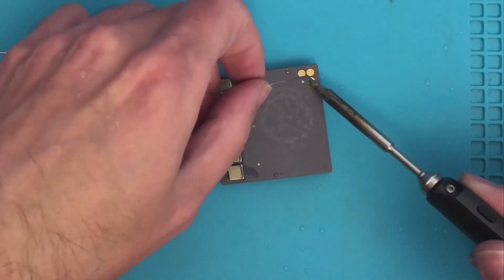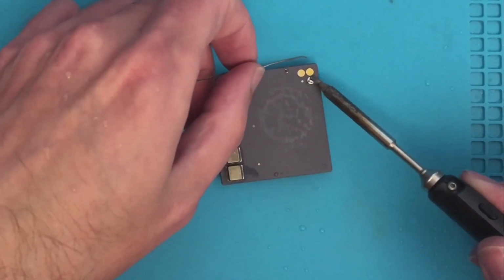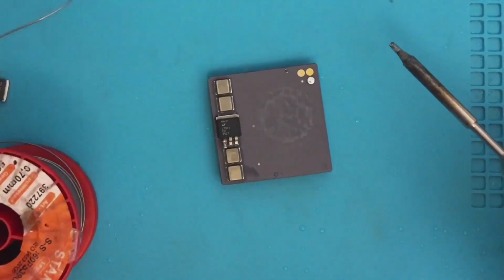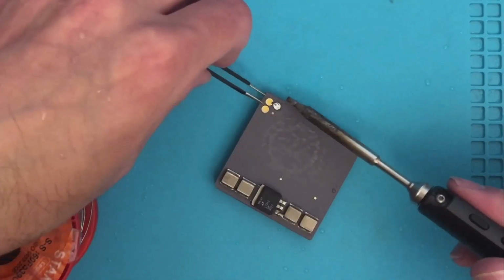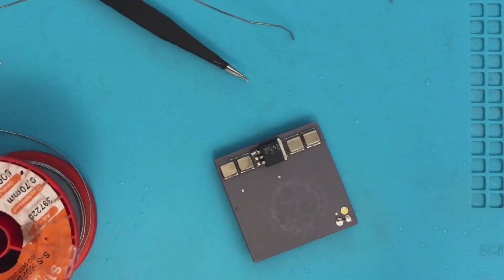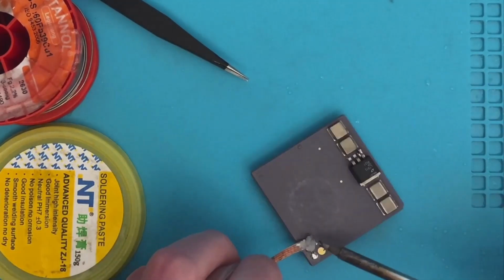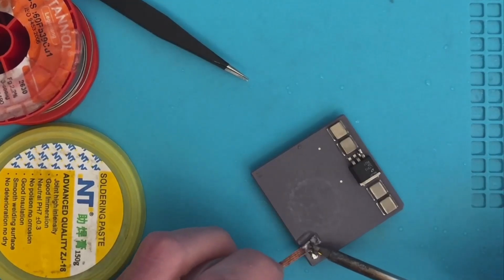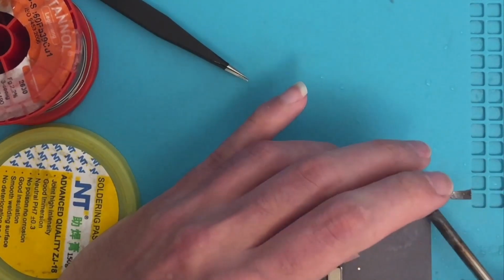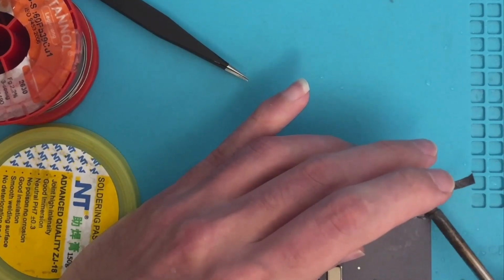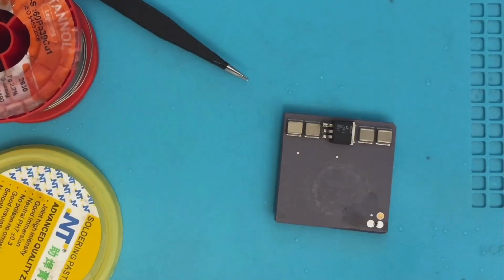So here is the very small SMD resistor, and of course I apply some solder first. Then I solder the resistor from one side and then the other. Of course at this point there is a lot of leftover solder here, and I want to clean this up so that I will have a big flat surface for the cooler. So I used some wick here with some flux and basically removed everything. The very little that is left is enough to hold the resistor in place. So yeah, this is the final result. I got in the end something super smooth here.